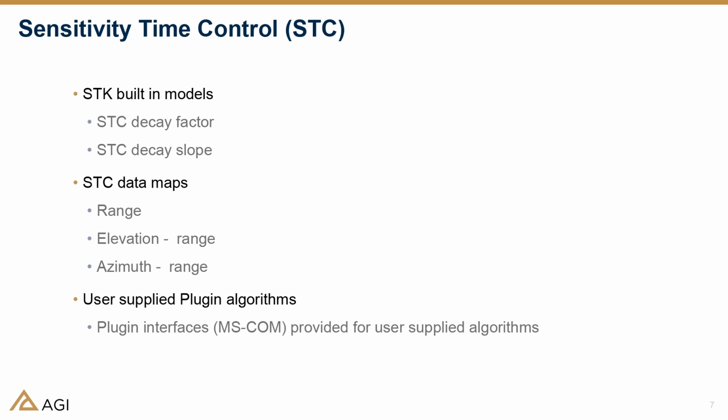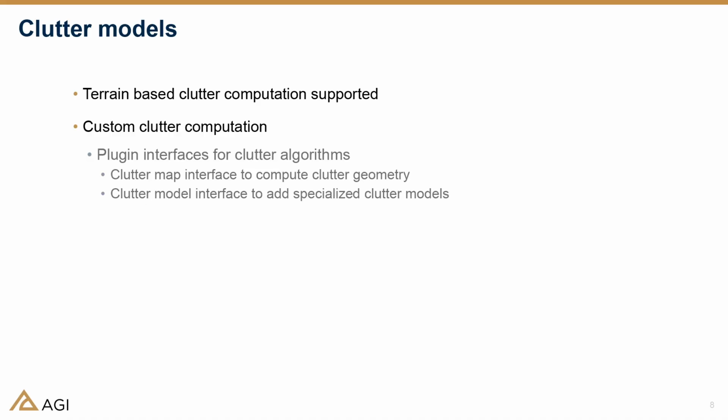We have different documentation that tells you how exactly you need to formulate that file, which is very similar to how an antenna file is formatted within STK, which is used for radars as well as transmitters and receivers. Like I was mentioning, there are clutter models that STK can handle too.